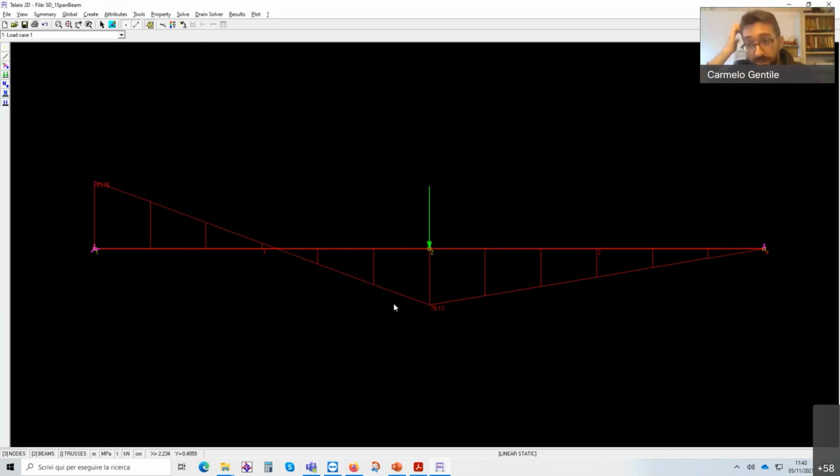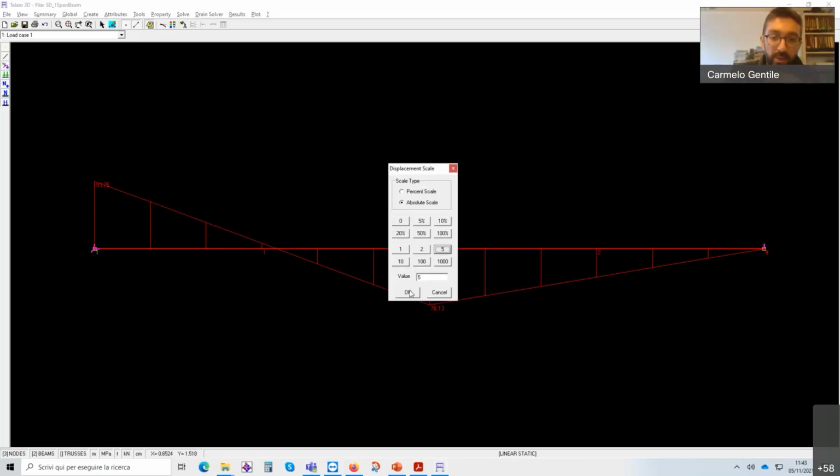This is the true result. In fact, we see that it starts from some value here, and that's what we expected. We expect a bending moment here because we have a clamped section. So if the structure cannot rotate, there must be a force that prevents the rotation. And in this case, it is the bending moment. And it is negative because we usually expect it, I said it several times, in the internal points where the, okay, let's go back and plot them all together.